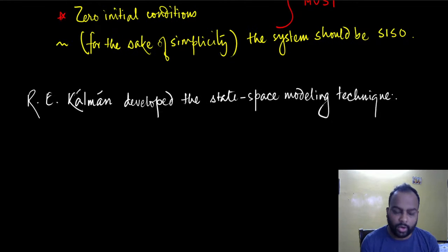Okay, you studied the root locus technique. Of course, that was a fantastic technique, and quite wonderful. Without actually solving anything, we are finding the locations of the closed loop poles for varying gain in the forward path. We're solving for the roots without actually solving for the roots. But if you ask a computer program today, will it apply any rule of the root locus? No. It will just vary the gain, calculate the roots and plot it on your screen. Just like that.